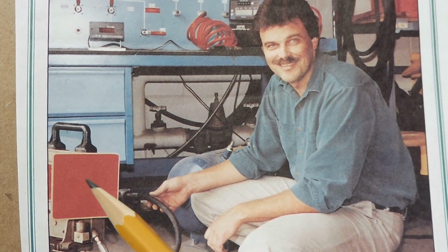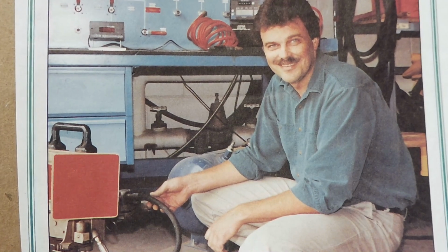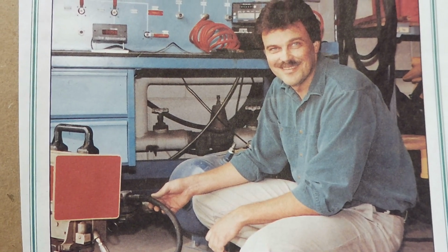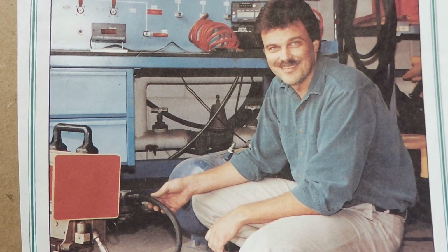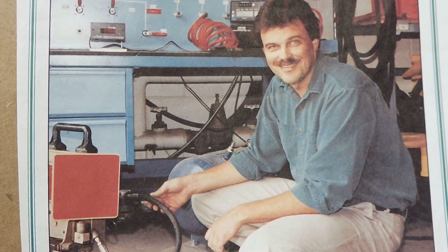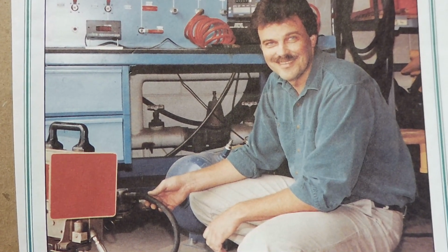So this device is clamped onto the last car of the train, and it sends air pressure and motion information to the head end of the train. It uses a radio in the 450 to 470 megahertz band, and it uses FSK to send information to the head end of the train. So this is another example where we're still using FSK in radio transmissions.